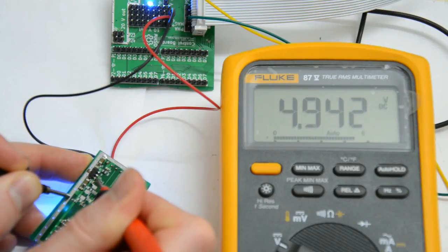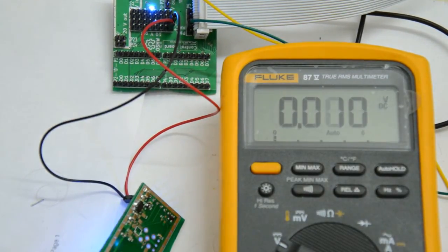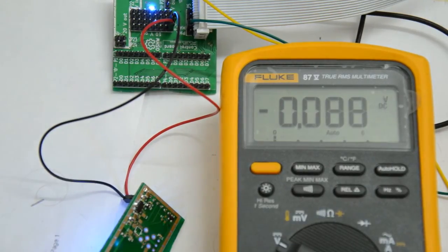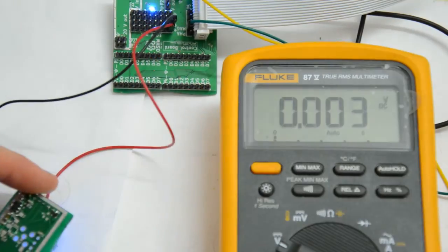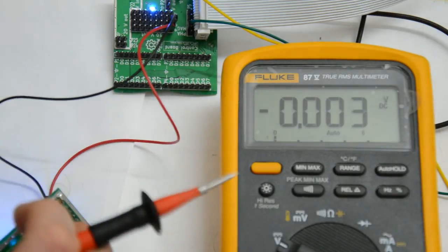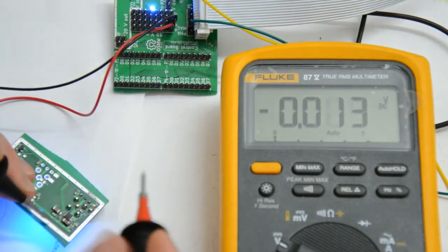And it's 4.942. So that's exactly what I was talking about before. If you assume that this is 5 volts, but in fact it's 4.9 something, then all your measurements are going to be scaled by that factor. So you have to be at least aware of that and not design it like that if you really care about that kind of accuracy. And then the documentation actually says that I should measure the input of the ADC without anything connected to it. And that should be about 30 millivolts. So I'll try to do that as best as I can on camera.